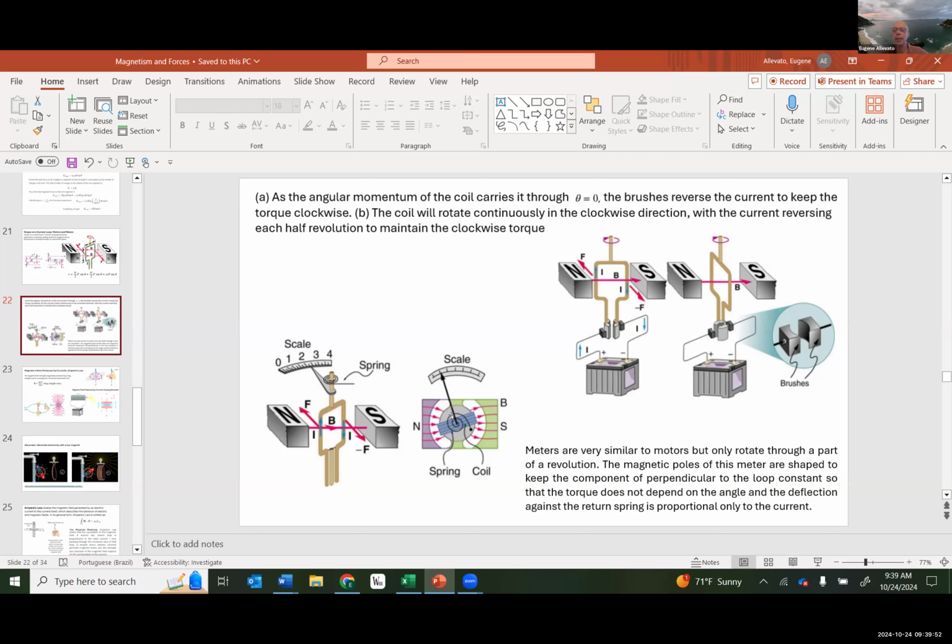I remember on the first day of class, I showed a way to measure current, a big instrument, and that is a coil inside with a magnet that makes this needle move in one direction or the other, depending on the strength of the magnetic field that's being generated there. So you're able to measure the deflection and make a scale, right? Calibrate the instrument with a certain current.